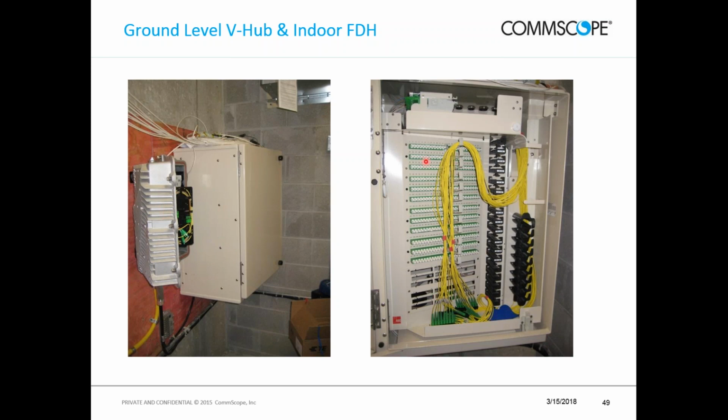The picture to the right shows the front subscriber access panel, and I believe it looks like maybe 1 by 32 optical splitters have been plugged in up top, and their pigtails routed down. It looks like they're in the process of identifying the subscribers and terminating the outputs of those splitters.